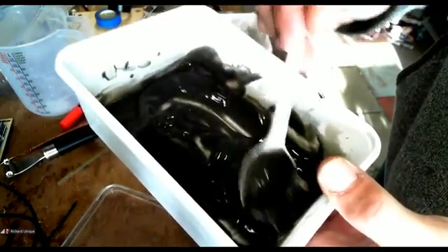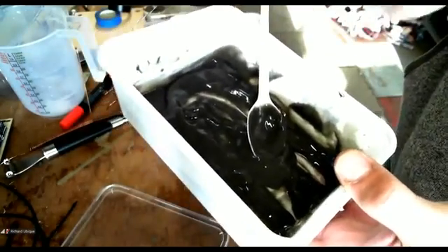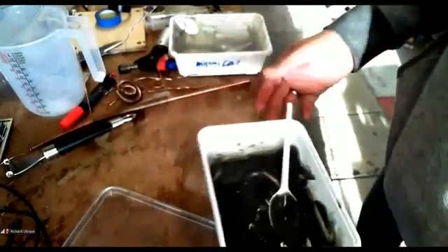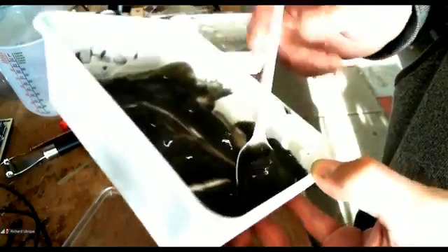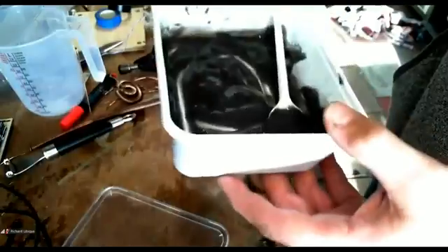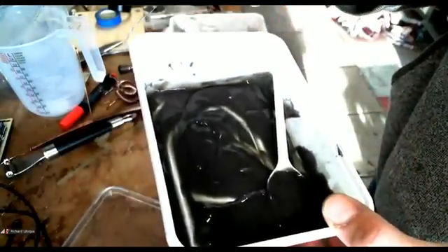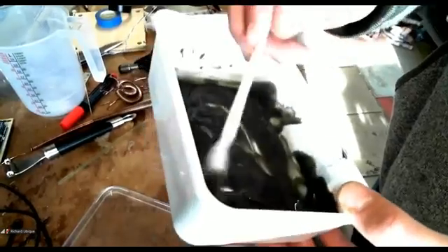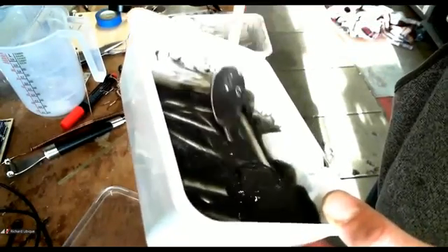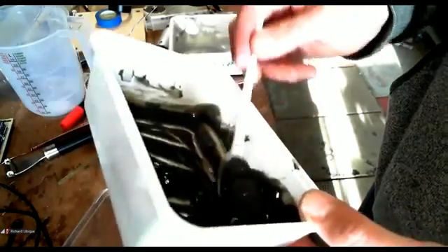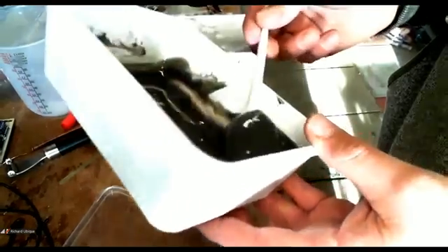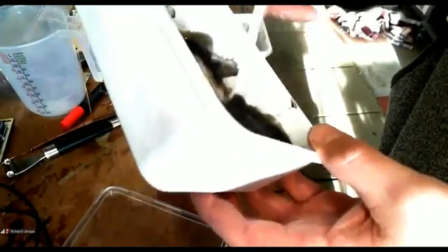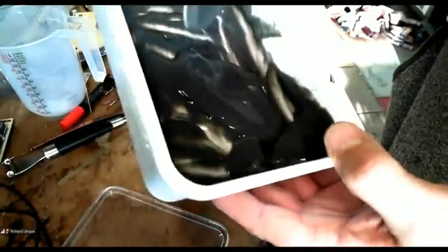When you dip your coils in this, it's really like a film getting on top of the material. You have to make sure that you inject this more or less inside your coils, because you already closed your coils. When you put it in there, you can just shake it around, and the liquid just goes through the coil. Just be careful, sometimes it doesn't. You really have to see that it goes through the whole thing. If you can inject it through, so that it goes all the way around, you'll find you don't need a gap. And that takes a couple of days to dry. Yeah, it takes a long time.